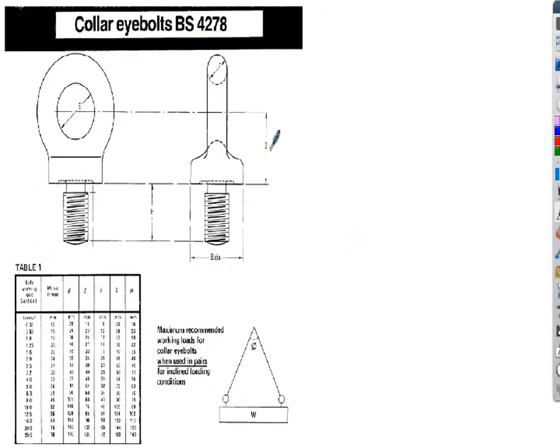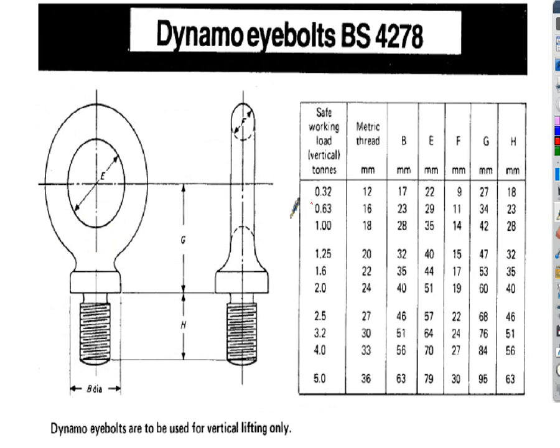If you've ever seen eye bolts that are used for lifting things, you have the threads, shown here diagrammatically, and these threads are actually in shear as well. So you get shear in threads, for example. They have to be designed to take the shear stress. Again, another eye bolt showing the thread that's in shear.